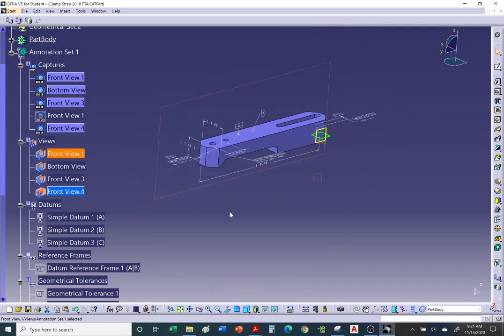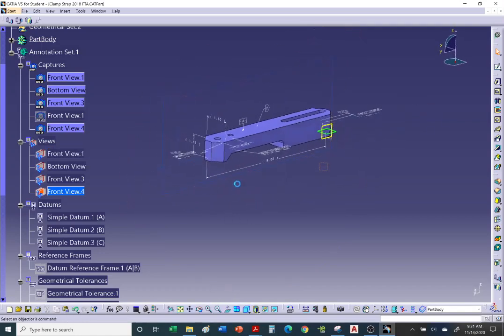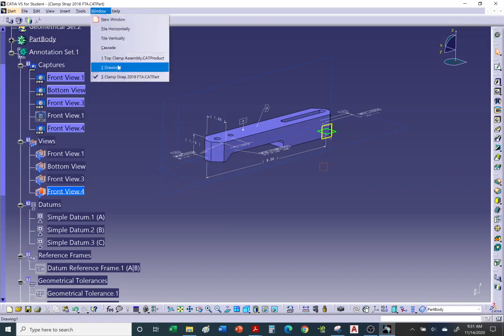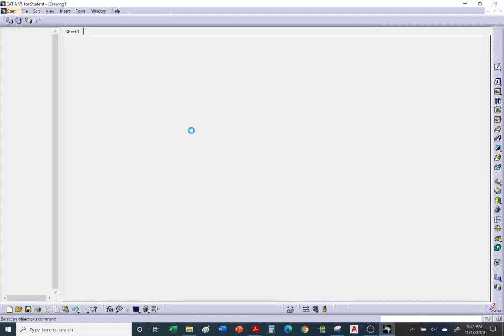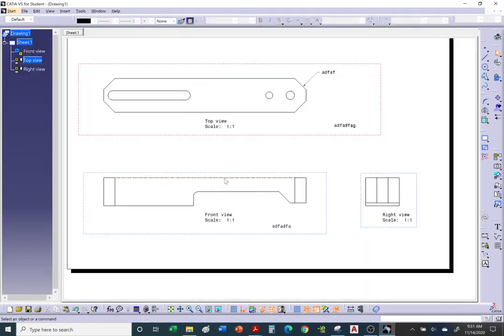And let's talk about view frames. So again, view frames are similar to what we see on a drawing. As I mentioned earlier, if you want to add text to a view, make sure you first double click, make it active, and add text so the text is attached to that view and also to the view frame. Okay, let's go back to the 3D model.